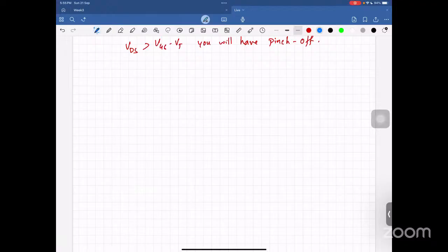But now after listening to your explanation again, I got the doubt. Then how will the depletion region actually influence the inversion charge? Of course it does, right? For that, there's something called the short channel effect on VT. I think in week 10 maybe I would have discussed it.